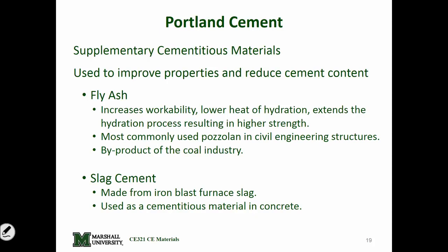We can add fly ash or slag to the concrete to replace cement because it's cheaper. Because it's cheaper, these actually become and replace the cement. So these are actually included in the weight of your cement for your water-cement ratio. Fly ash has advantages. It doesn't get real hot. Slag has its advantages. They're trying to give it away like candy.